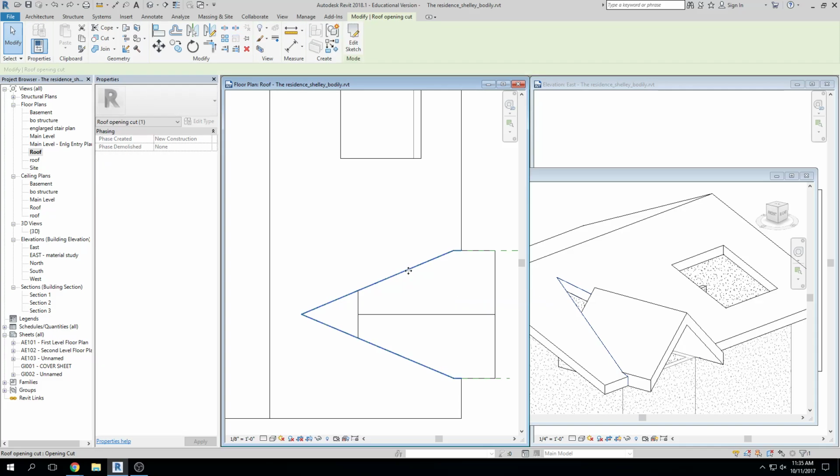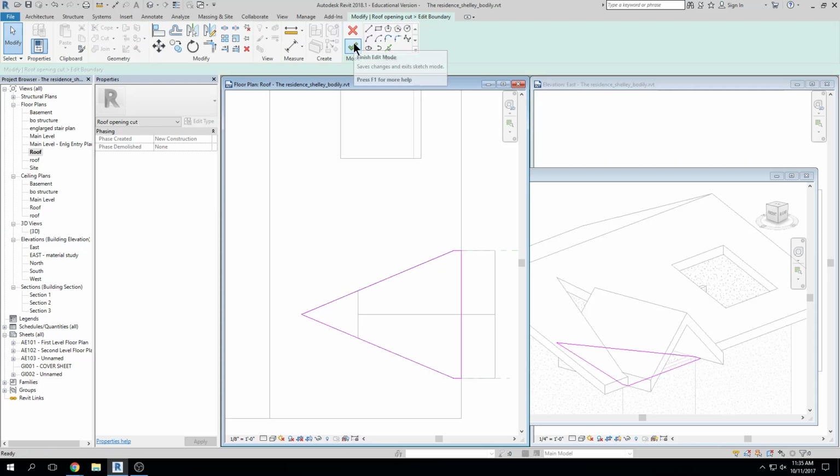I'm going to grab my roof opening, which you can click on and hit edit sketch just like any other thing that you sketch here. And I'm going to use the pick tool. I'm going to offset my sketch 12 inches to the inside. So now the 12-inch thickness on this roof has that area to connect to. Does that make sense?